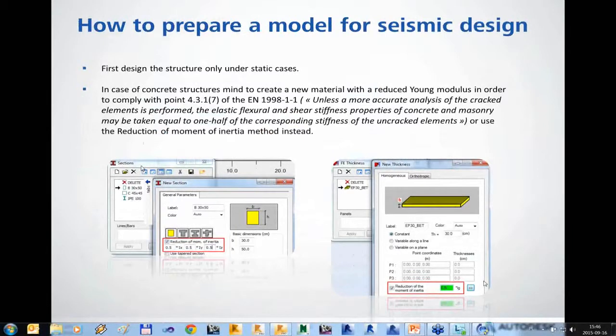And there's another one, and basically it is when you want to run a seismic analysis or spectral analysis with different factors, with different parameters. In this case, you may need to create several different load cases with different parameters and then use them, for example, for SLS or ULS check.